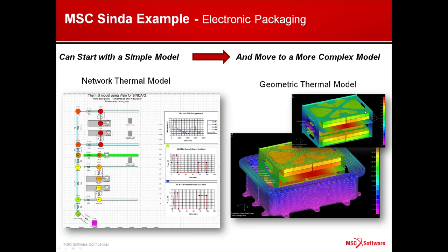And we needed to get the heat out of this package into the frame and conduct down to the base that was mounted on a radiator in a satellite. And so I cut this frame right in half and built a simple network model just to see what was happening. I wanted to see if I was going to get my energy out of these hard disks through their mounting resistance, through the frame, and out through the shock isolators.